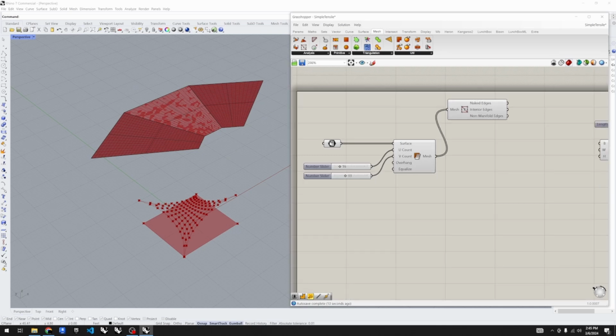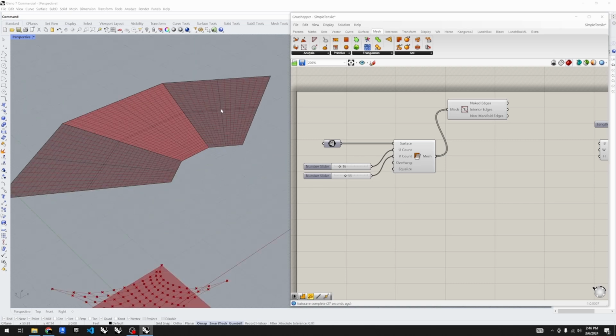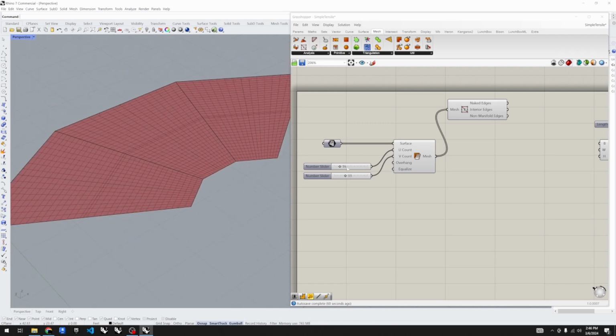Okay. Another thing to note, if I just hide this, we can see we're getting different colors for our meshes. In some ways that can be distracting, in some ways detrimental. I don't think it'll have an effect on our solution here, but just to make sure everything's uniform, what happened was when I mirrored across this plane, like if you were flipping a pancake, these normals are upside down compared to these ones. So an easy way to fix that, I'll select the surface in Rhino and type in flip as a Rhino command, and I'll flip that surface and do the same thing over here. So now they all point up the same direction and we should be okay.